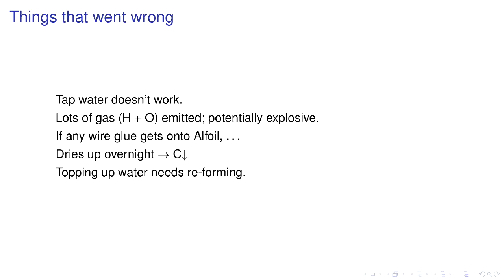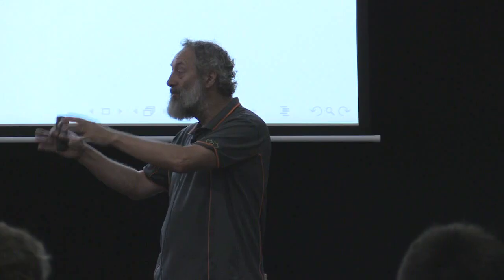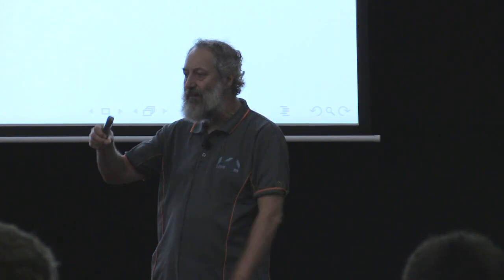And for short term, you probably don't, because you can pull the aluminium foil out and it reduces the capacitance, you can put it back in and it increases it again, which, by the way, gives me a really good idea for a variable capacitor. Typically, if you make an air core, your commercial variable capacitors go up to maybe 500 picofarads. With something like this, if you've got a scrap of aluminium dipped into an electrolyte, you could probably make about a 500 microfarad variable capacitor. But I haven't done that yet.